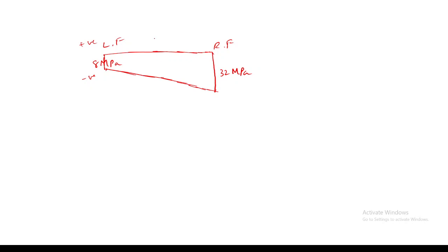So can you find out, this is the total length 100. Here where is the neutral axis actually going to lie? Left side, yes. If you extend this, you will get to know this is the position of the neutral axis. Again, by using similar triangles, can you find this? Let us take this as the distance x. Can you say what is the value of x?